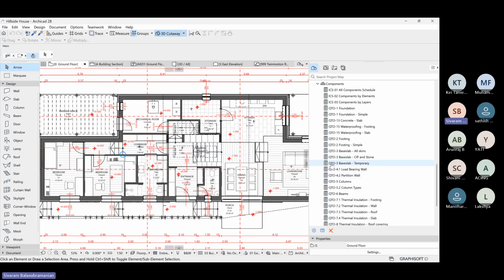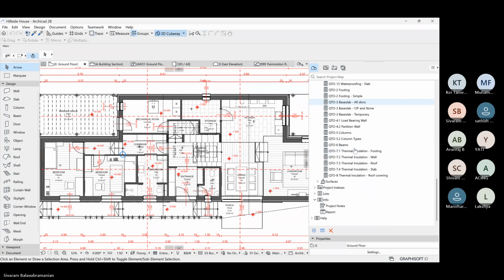Components that will have all the, for example, if my wall, I'm also adding plasters to my wall later, so that will come as a component of the wall. So I can take out a component level schedule like load bearing walls, partition walls, or just insulations of these things. And then we also have surface based schedules.